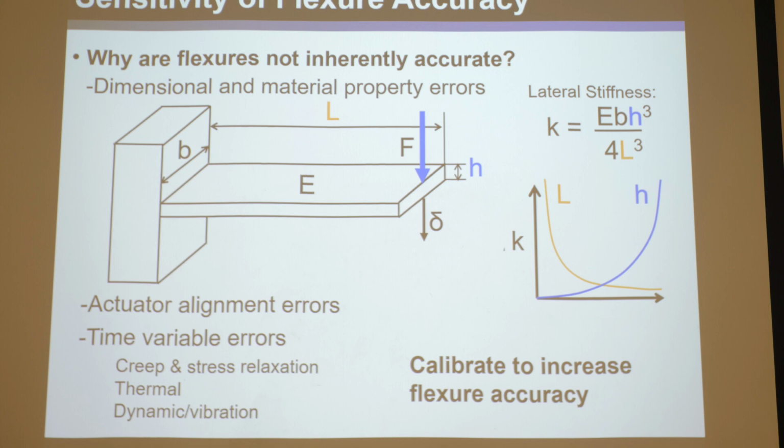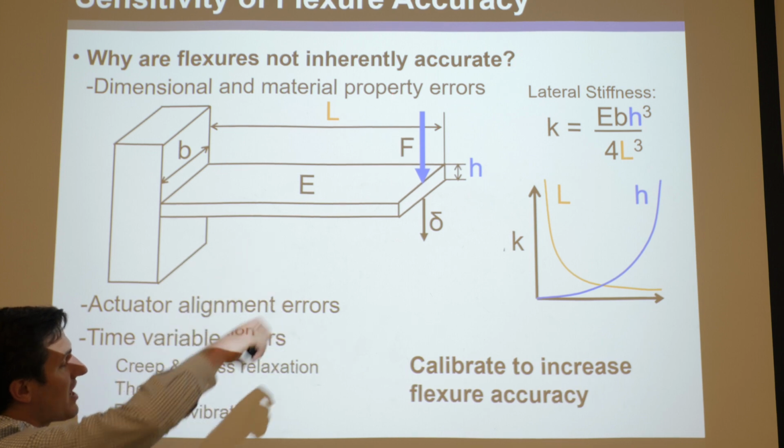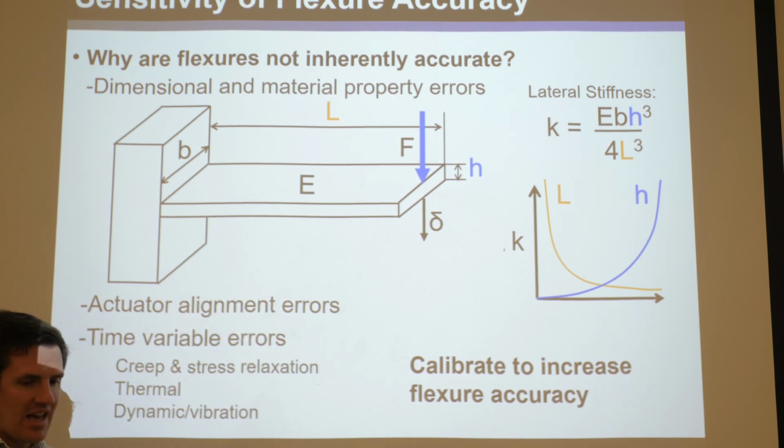Stress relaxation is kind of the opposite. Instead of applying a constant force, you apply constant deformation. Say I put a big ball under this and deform it up and keep it deformed at the same curvature over time. Initially, there'll be a bunch of stress in the beam, but over time, if it stress relaxes, then that stress will go down, and when you remove the ball, it'll remain permanently deformed, right?